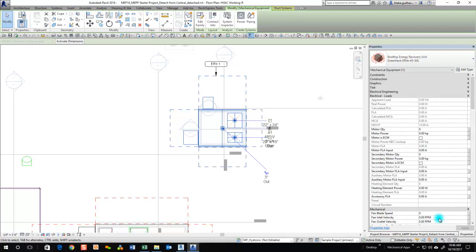So what we have in electrical loads is all the different types of motors that equipment might see, and we've started to determine all of their loads. What electrical is after is full load amps, and what mechanical has to offer is quantity and size of motors in horsepower ratings. So we've included the NEC table 430, which has rated full load amps for different types of motors based upon voltage and phase.